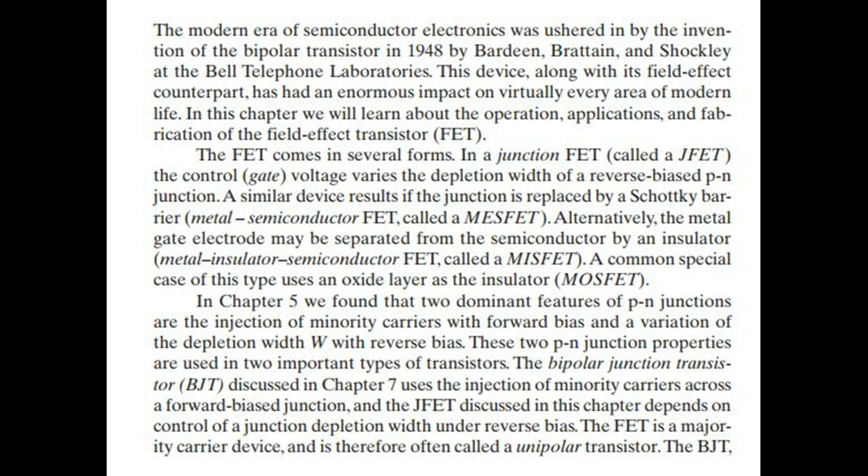The FET comes in several forms. In a junction field effect transistor, called a JFET, the control gate voltage varies the depletion width of a reverse-biased p-n junction. A similar device results if the junction is replaced by a Schottky barrier, called a MESFET, metal semiconductor FET.